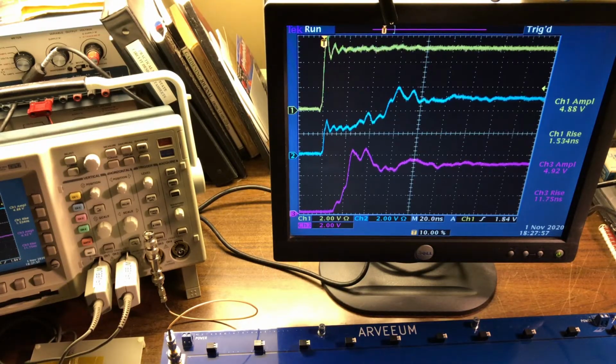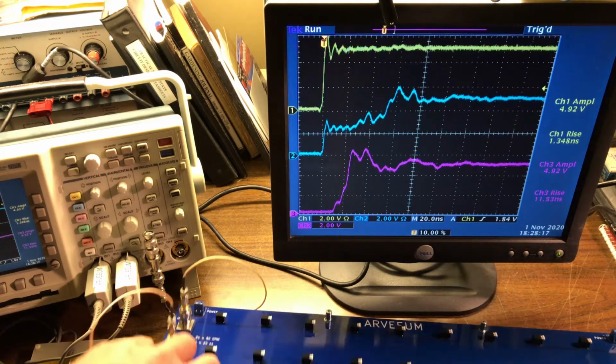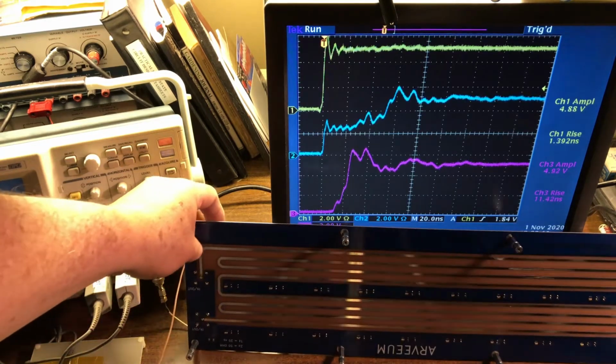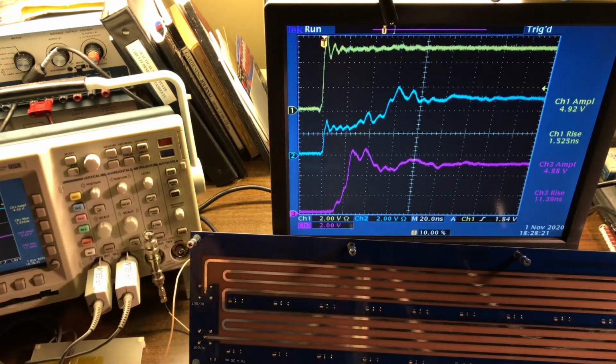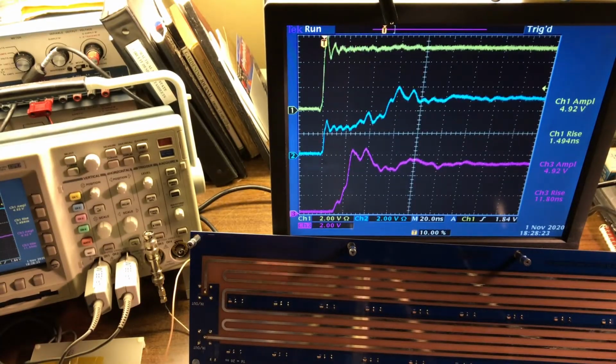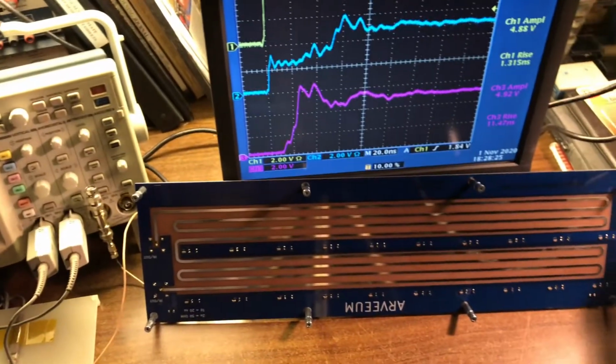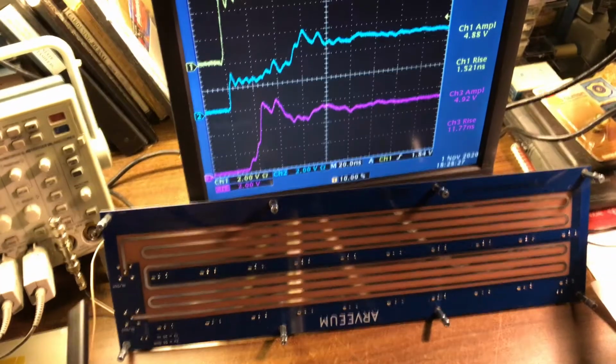We're now going to do 2 experiments to demonstrate the effect of lack of proper return current path for the microstrip in this board. Let me show you first how the board is made here. So the board at the bottom has a long microstrip, 20 nanoseconds long, and as you can see, is divided in 2 sections.